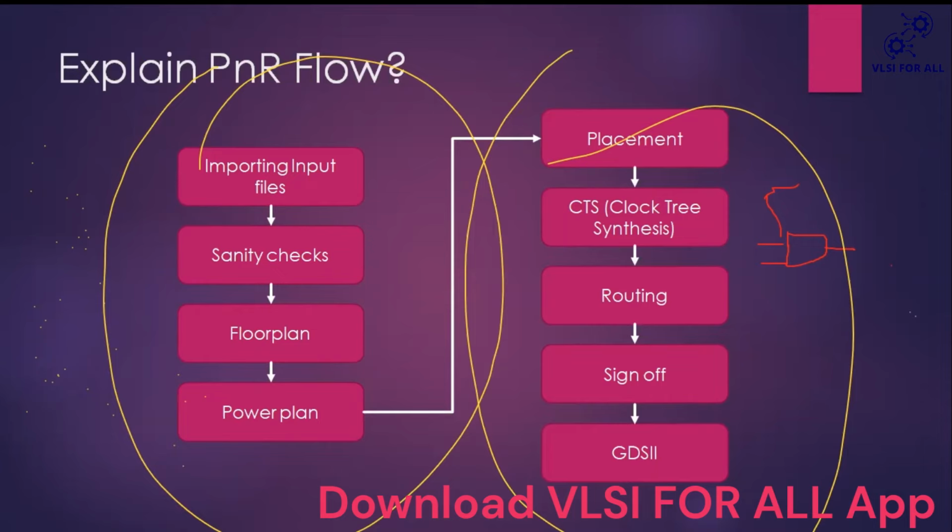The netlist given by the synthesis engineer should be cleaned up of errors like combinational loops, multi-driven nets, or floating inputs. It should be clean of every issue. These are very serious issues, guys: combinational loops, multi-driven nets, and floating inputs.